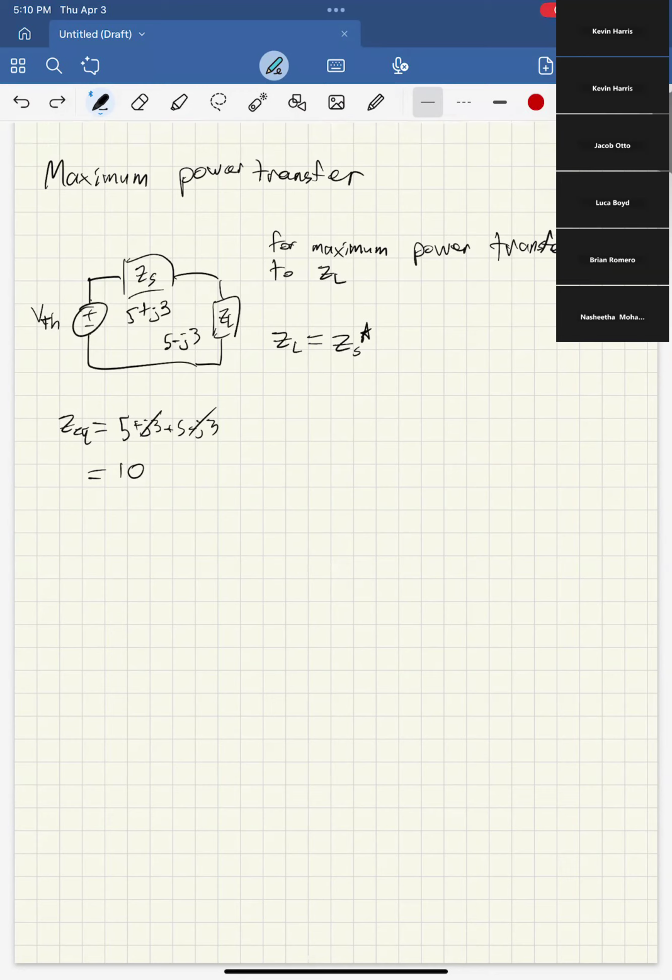So cool. And then you make the real parts the same. That's just like what you learned in the first half of the semester. You can either accept this as fact, or look it up. And then the nice equation that's the result of all of this is the P average, not S, the P average max. So the maximum power you can get in a scenario like this is going to be 1/8 times the magnitude of Vs squared over RL. And key point, this is RL.